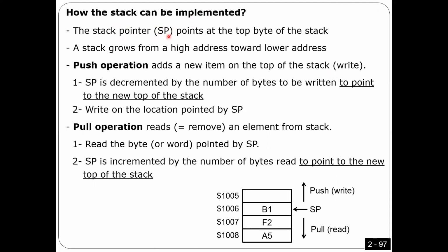And I told you I'm not going to talk about this register now because this is completely different from register A or B or X or Y. It's not a general purpose register, so I'm not going to use it in calculations, addition, subtraction, something like that. This one has a special function: it should point at the top of the stack. So always the stack pointer should store the address. That is why the stack pointer should be 16-bit, because it always should store an address.